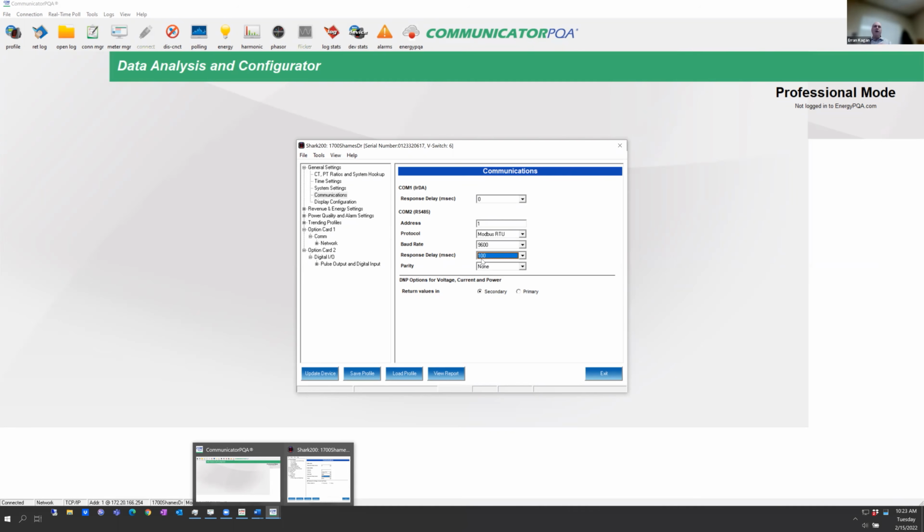converters to flip. Our Unicom 2500 actually has a little microprocessor in it that's listening to the end of the message and flipping it for you, so you can have a much shorter response delay. But the standard ones that you buy from distribution, they're not great with this. So you may want to put this. So if for some reason your 485 is not working, that might be a place to look. And it's always a good first place I start with debugging.